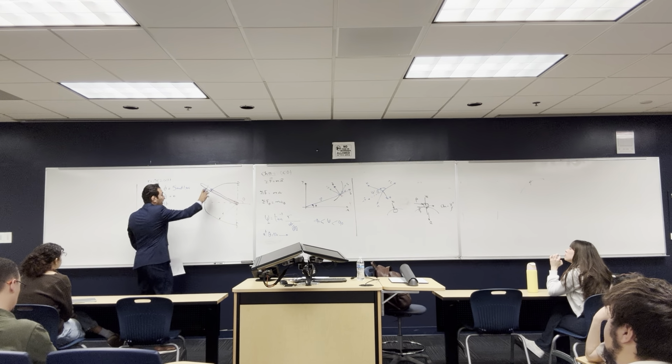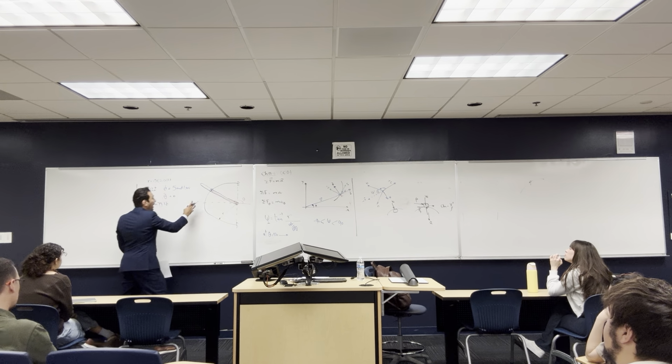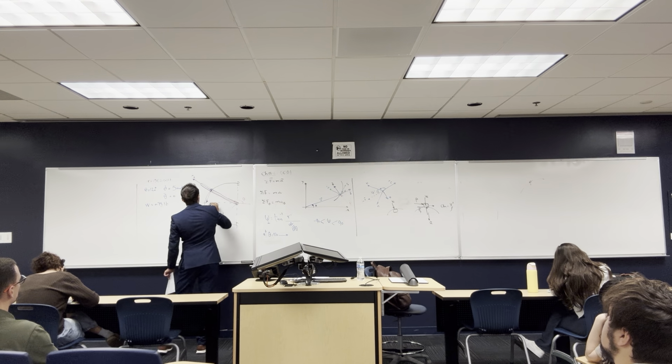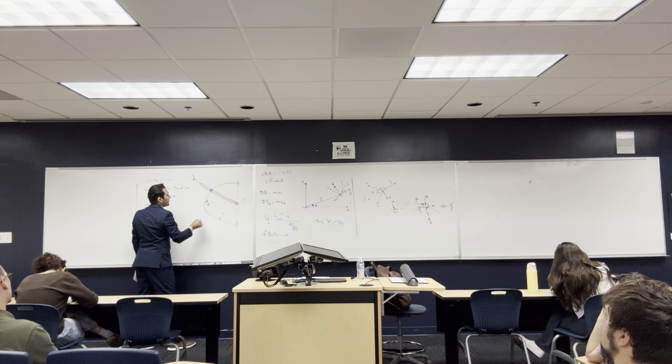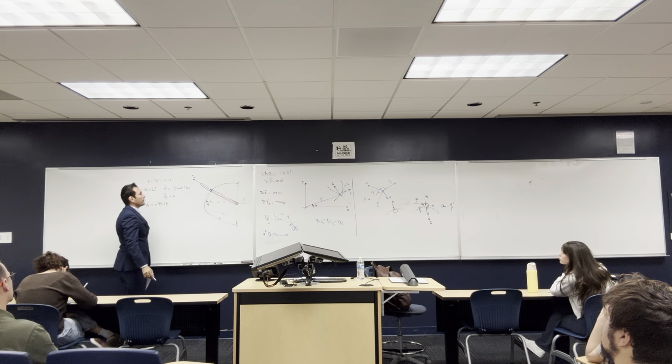But to do this, before I take this body out and map the forces, I want you to find out with me what is the tangent, normal, and what is the r and theta. Okay, r and theta is very easy to do. I'm going to use the same colors that I used here. Let's find r and theta. I'm going to use purple. So r is going that way, so r is always in the direction of the arm. That is r hat. How about theta direction? Theta direction is always perpendicular to the r. Like if r is that way, so that is the theta, in the direction of increasing theta. That's the theta hat. And the angle between them is 90 degrees.